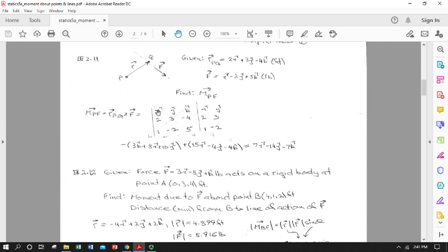But for this determinant method, you just basically create a matrix that includes your coordinate axes on one line, and to make it easier to write out, you just repeat the first 2 columns. You put your first vector to be crossed, which is of course, to calculate moment, always going to be the radius, on the next line, and repeating the i and j, and then force on the last, and then literally multiply along diagonals. And then when you go from left to right, it's positive.